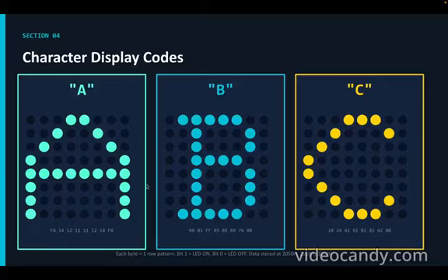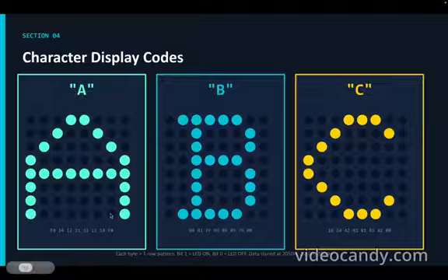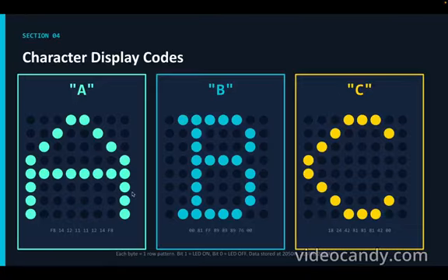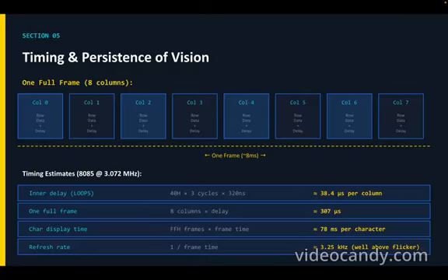But if you do the experiment, you will not be able to observe anything similar. You will see that it's being printed properly. Why that happens is because, even though we are outputting only 8 bits of data, which is only one column, the 8085 microprocessor can work at a refresh rate of around 3.72 megahertz, which is its internal processing speed per cycle.